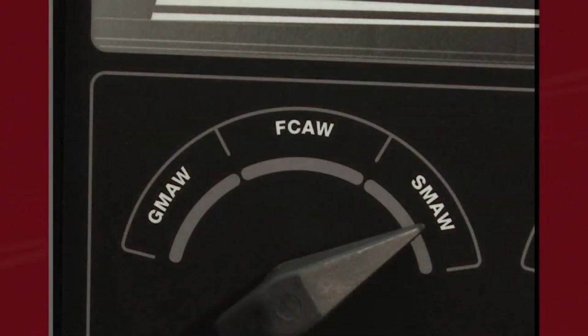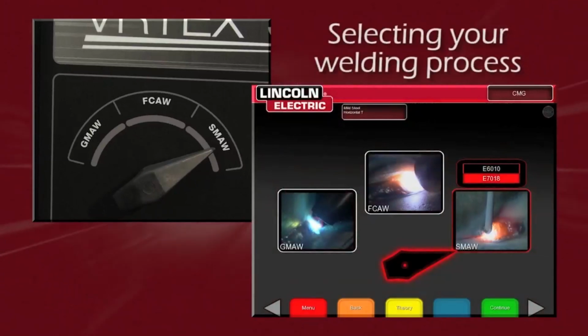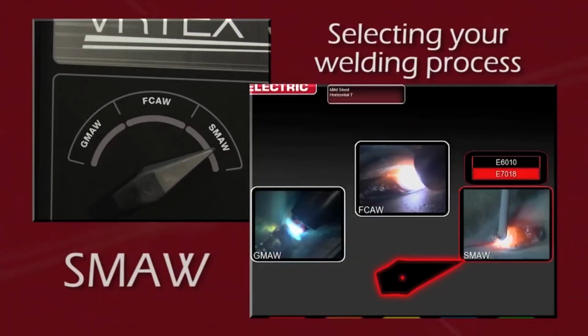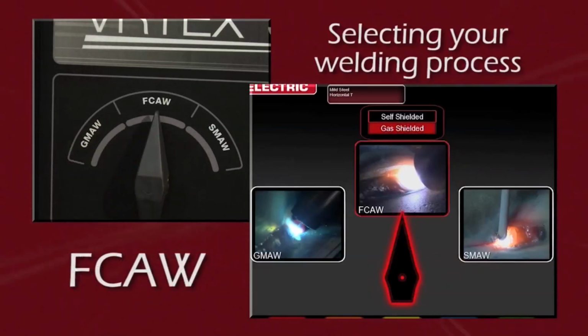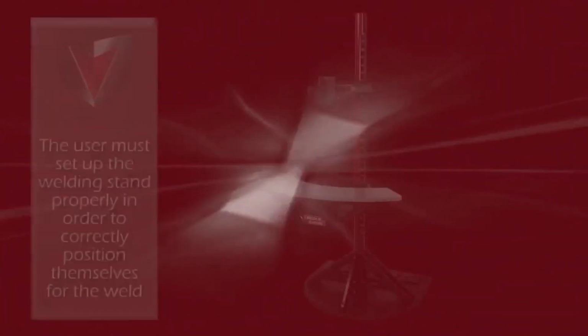And now it's time to select the welding process. Turn the process selector switch on the front of the machine to the desired process. The available processes are SMAW welding with 6010, 7018, and 6013. FCAW processes using both gas and self-shielding consumables, and GMAW using short circuit, axial spray, pulse, and surface tension transfers.